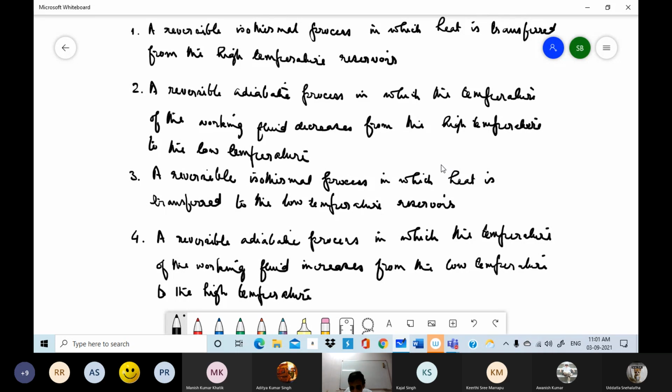So then if you want to plot this, one coordinate would obviously be temperature, so that the isothermal processes would be straight lines parallel to one of the coordinates. What about the reversible adiabatic process? If we can find a coordinate where an adiabatic process would be a straight line, then the Carnot cycle would be a rectangle.